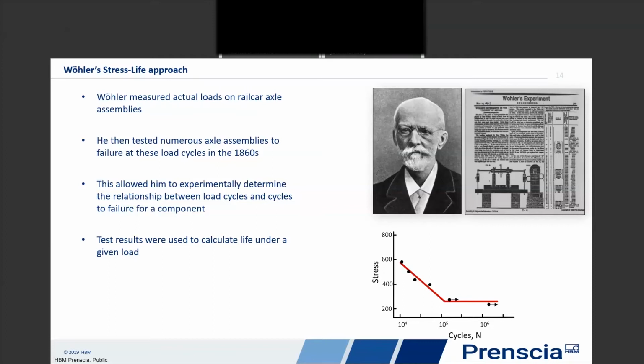His real emphasis here was looking at the fatigue curve where it goes horizontal on the bottom right-hand side. What he saw with constant amplitude loading, at some load level, he never saw failures beyond less than that load level. So it was a stress level or a load level on his part that he was able to control to guarantee he had infinite life.